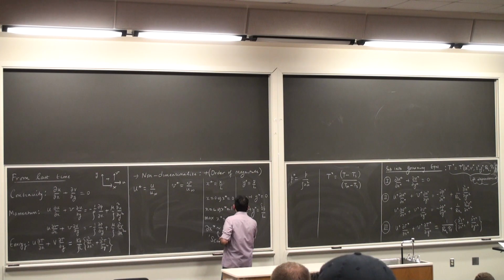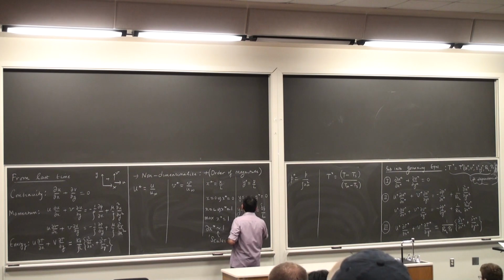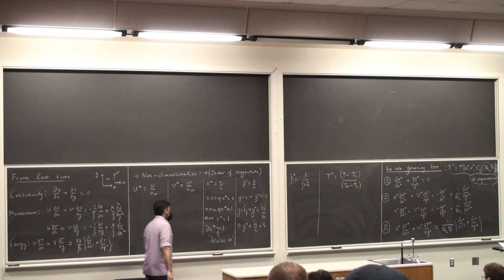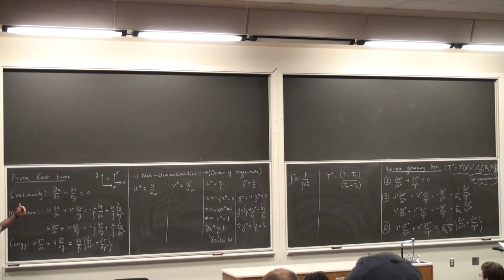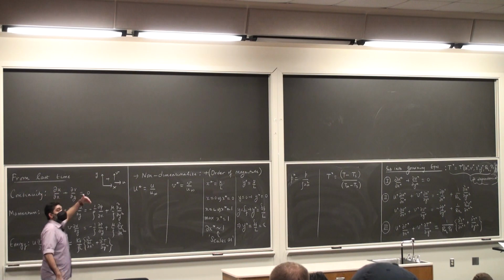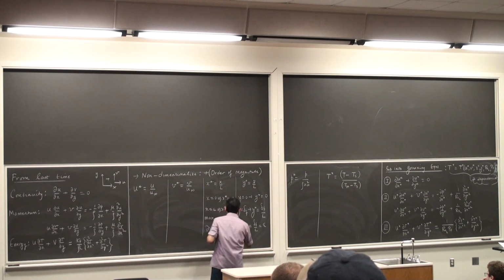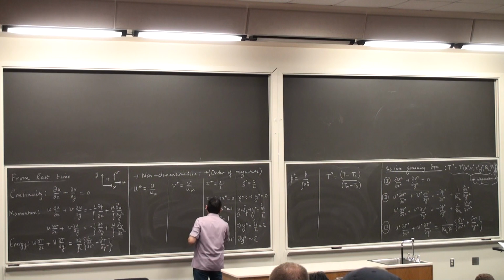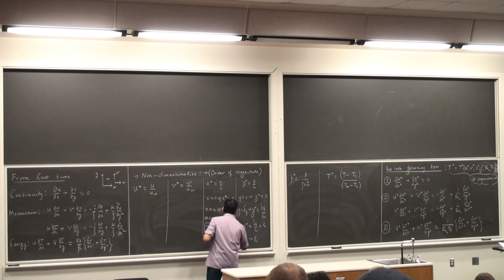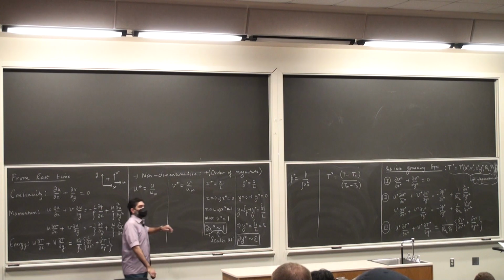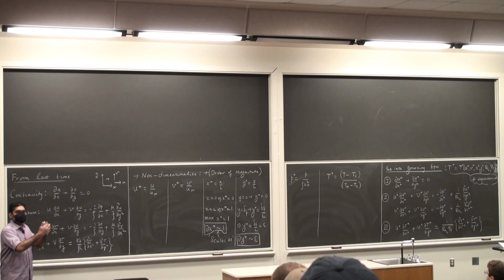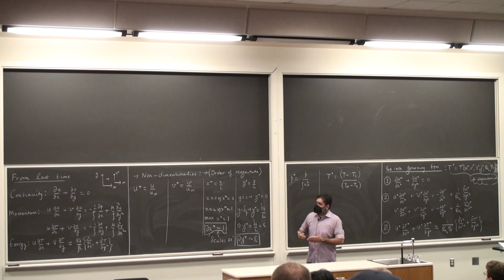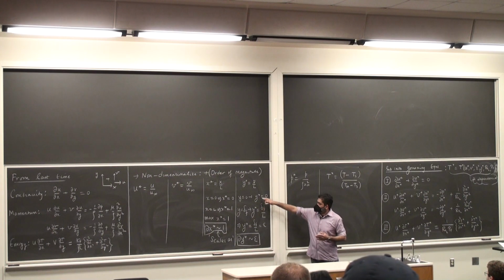So y star is equal to epsilon. And if I now take the difference between the maximum and the minimum value of y star within the boundary layer, this scales as epsilon. So d y star scales as epsilon. I want to see if this makes sense to everybody. You understand the scaling procedure, right? You have the maximum, you have the minimum values within the boundary layer. This is what is happening here. So this scales as epsilon minus 0, so that's epsilon.